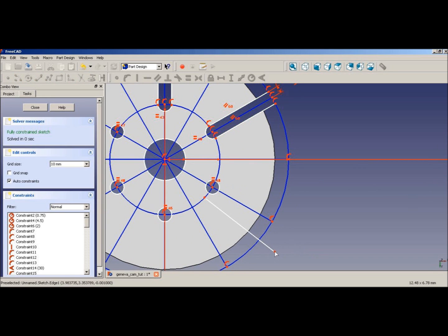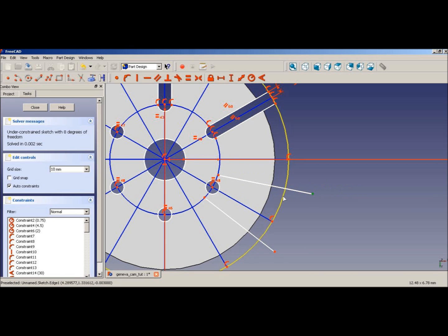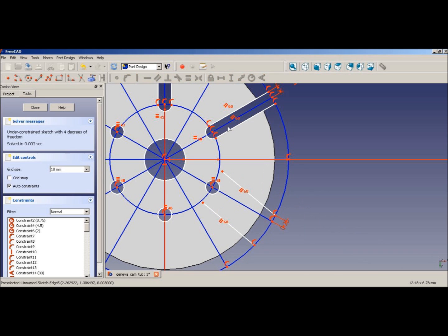I'll probably skip ahead here, but you get the idea. Constraint to the outer circle, constraint to the inner circle, constraint to the little circle, constraint to the center line of 0.25 of a millimeter, parallel constraint, snip out the unused section of the circle, and then reset those last two constraints. It's kind of a sucky procedure, but